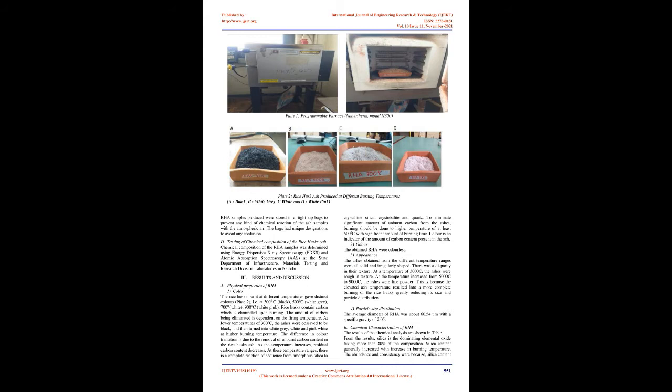Complete combustion was ensured by burning just enough rice husks, working with a shallow crucible so that the rice husks are always below the air inlet flaps, and allowing the RHA samples to slowly cool inside the furnace. Testing regimes incorporated were controlled isothermal burning, temperature variation, constant burning duration of 3 hours, and slow cooling of the RHA.